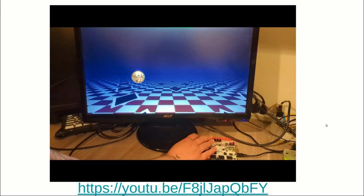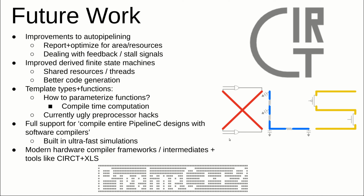All right. And of course, finally, I wanted to touch on some future work for the project here. I'm always looking for help. I love discussion of new features and things like that. So the future is looking at things like improving the auto-pipelining. Right now, it doesn't optimize for area at all, or report it even. And then next is dealing with those feedback and stall and potentially combinatorial loop signals opposite the normal data flow.